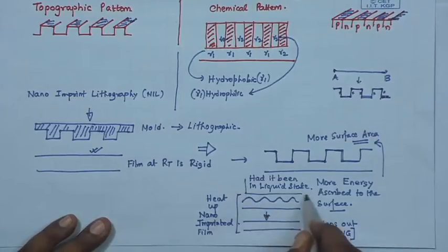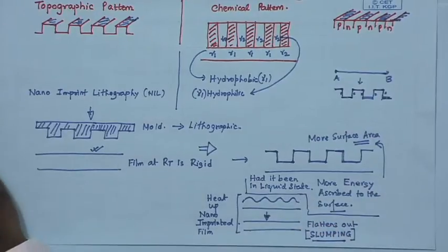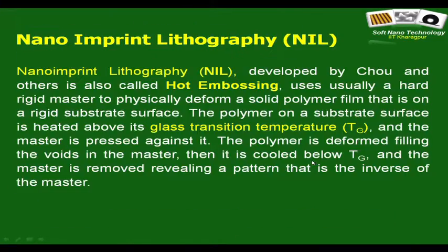But the advantage is, you are cooling down the film while it is in a liquid state, it is adhering conformally to the stamp, and therefore, it creates a negative replica. If you are using a polymer which has reasonably high Tg, let us say 100 degree centigrade, and you are down to room temperature, of course, we will understand soon, maybe in the next class, that these structures contain a lot of residual stresses, but the structures are permanent and they serve your purpose. So, this is what nano imprint lithography is. We discussed a bit of critical issues, I must admit.